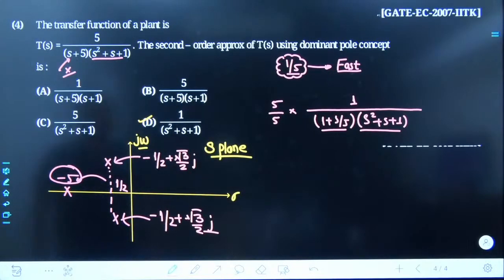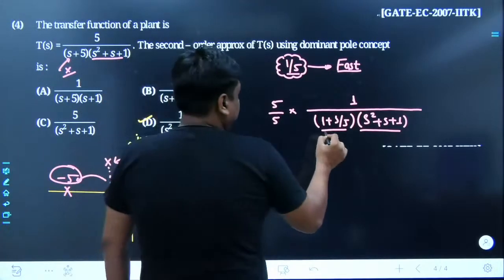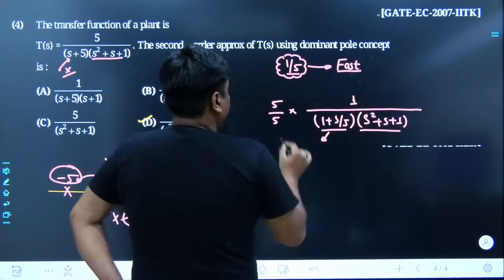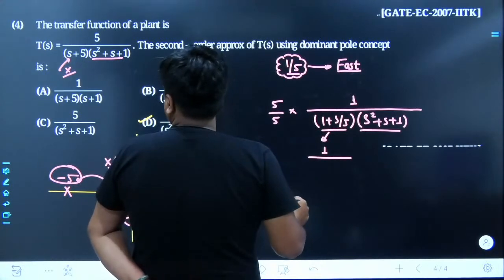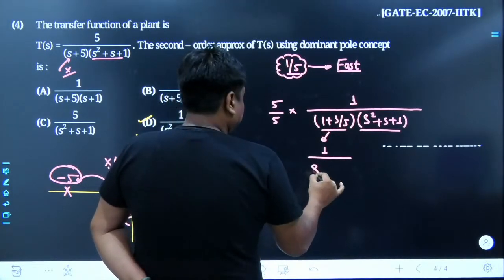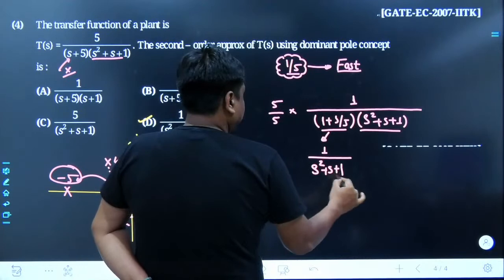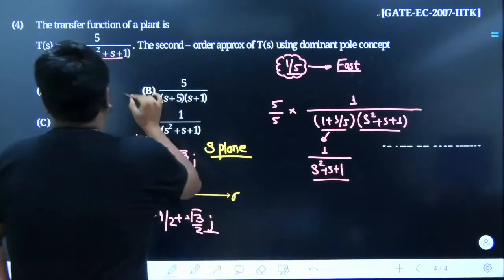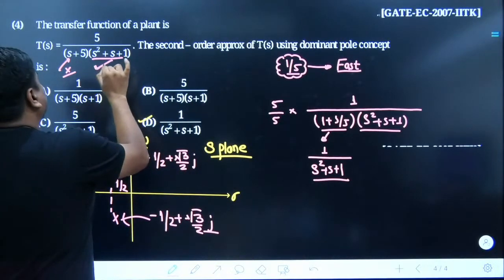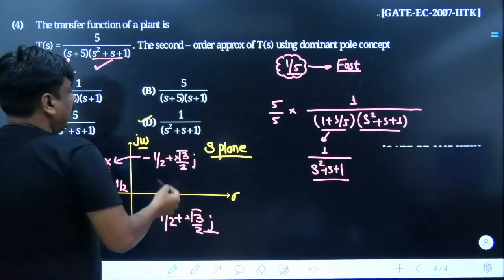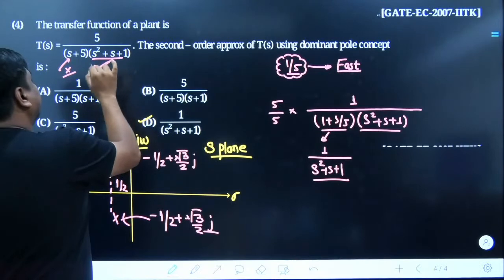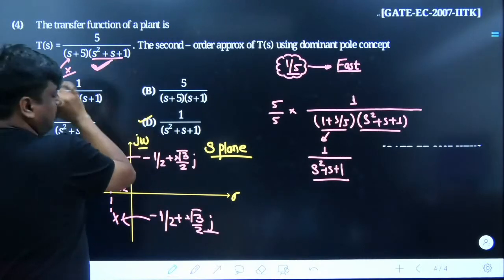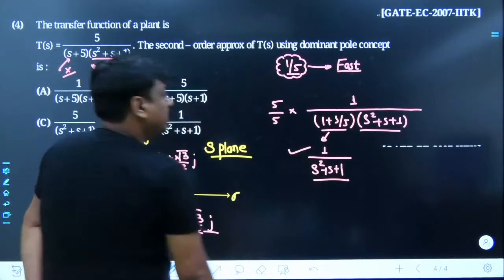So one thing is quite sure, yes sir, now it's the right time to drop this out, and once we drop this out, this is 1, and the factor which is left in our hand is 1 divided by s square plus s plus 1. Either you take the DC gain offered by this system, or you take the steady state response if the system is excited by the unit step. Through this or through this, you would get the same answer.